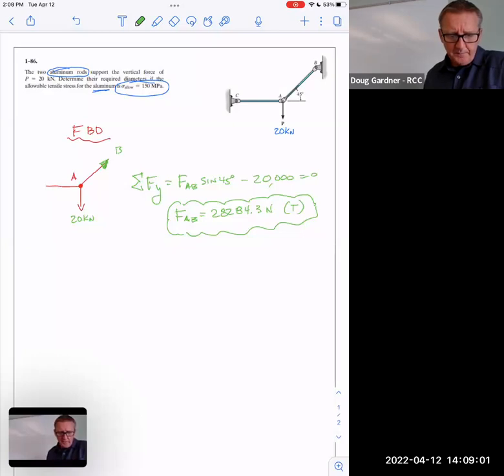Can I just calculate this? Well, remember, notice they said two aluminum rods, and they seem to be implying they're the same exact rod because they told us what's allowable. Well, I guess not necessarily, because that allowable doesn't talk about dimension. But we're assuming they're both the same. So can I just make my calculation off of this? Well, I might be able to keep AB from breaking, but what if this force causes the other one to break? I need to know how much force is on that one too.